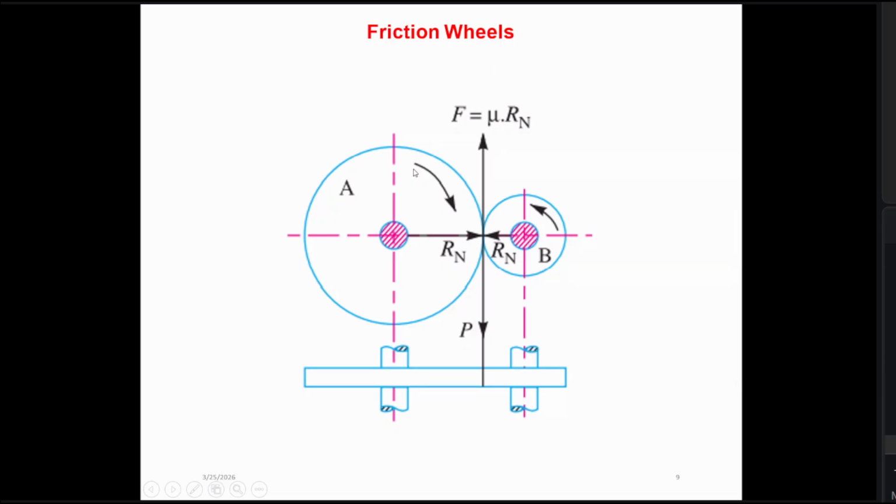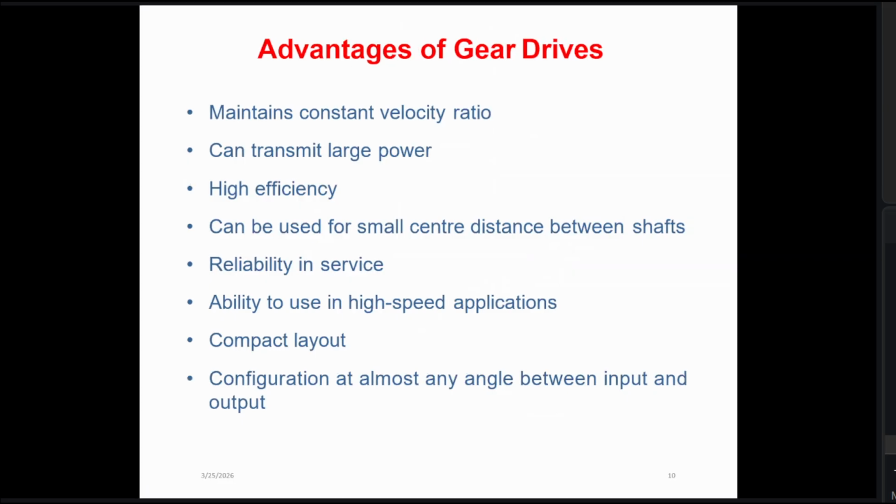Yes, in the case of friction wheels, as you know, the friction F equals mu R is the key governing factor there. According to the amount of reaction force acting on each wheel, we can calculate the frictional force. That frictional force drives the frictional torque, right? So in gears, the situation is a bit different. I will explain that later. But kinematically, these two are equivalent.